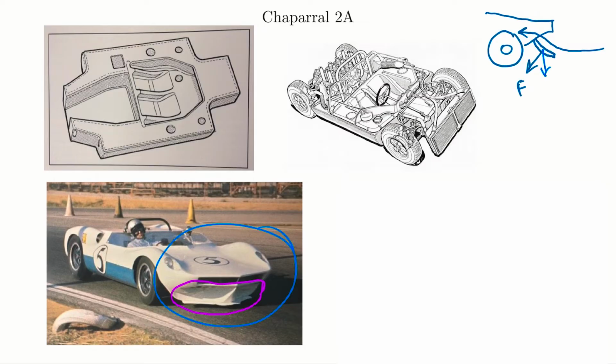And now I'll just show the two components of that. So that results in a drag force on the vehicle, but also a downforce on the vehicle, a downforce that you can control with the shape and size of the air dam. And you can see this keeps happening, right? So they have to solve a problem. So their problem was they had too much lift, right? And so to solve this problem, they learned to push down on the vehicle.